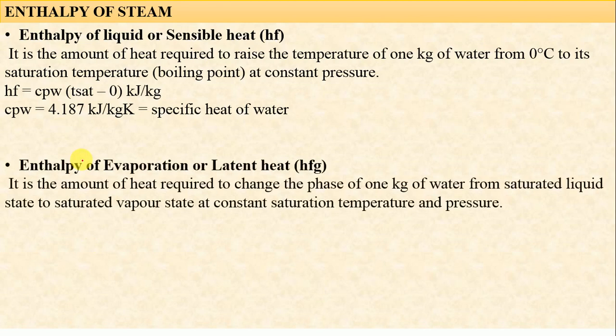Now the enthalpy of evaporation, or latent heat. It is the amount of heat required to change the phase of 1 kg of water from the saturated liquid state to the saturated vapor state at constant saturation temperature and pressure. In the graph we already discussed, 0 degrees Celsius of water is present, then on further heating this is the sensible heat, and this is the latent heat. This is your Hfg actually.